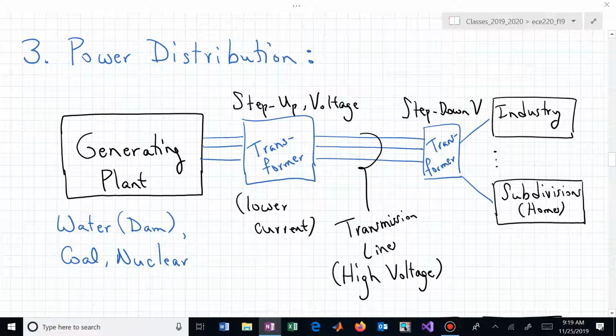And we'll talk about this sometime. We'll have to figure out how to transform what we've been using, which are these maximum voltages, to an RMS value, but we usually refer to these outlets in RMS units, and that's 120 volts roughly. The peak, or the amplitude of those waveforms, is higher by a square root of 2 than the 120.